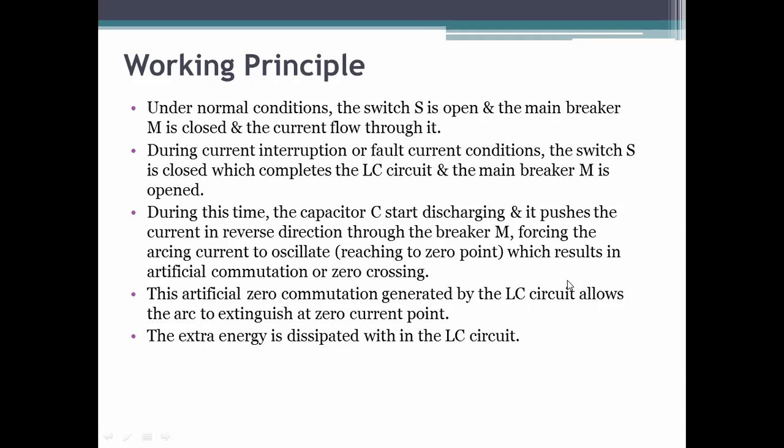This zero crossing generated by the LC circuit allows the arc to extinguish at the current zero point, and the extra energy is dissipated in the LC circuit.